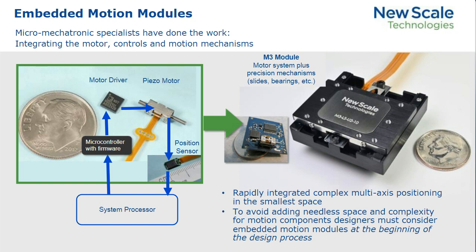We use advanced ceramics that allow us to directly drive the motor from 3.3 to 5 volts. There's no need for an internal voltage boost. This has really enhanced our integration capabilities, and we actually have a single chip drive that you can see in this image next to a dime.